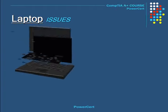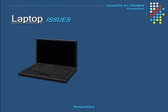Now, as far as troubleshooting issues with laptops, one of the main problems is that when you turn the power on, your screen is blank. Nothing shows up on the screen. Now, you may hear the fans running, and you may see the LEDs turn on, but your screen is still blank. And this is called a no display issue.